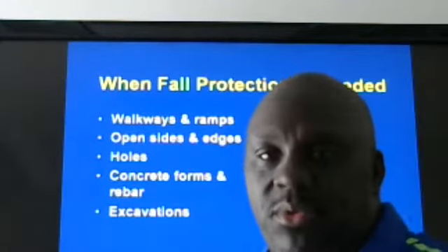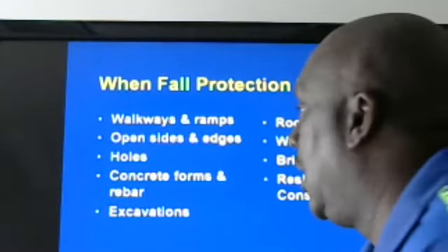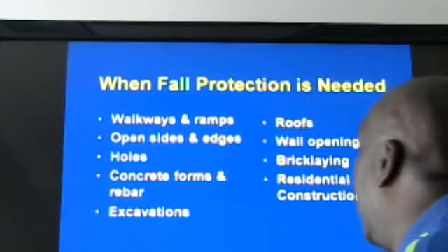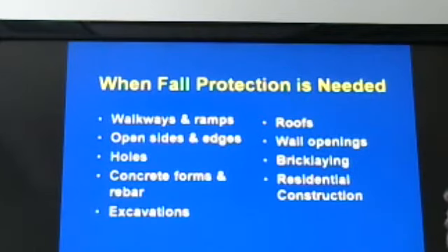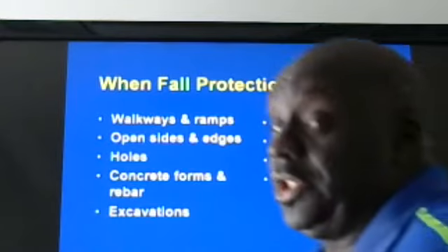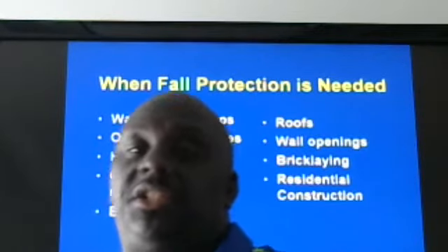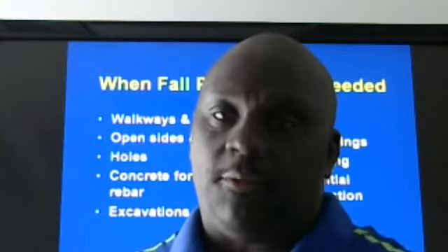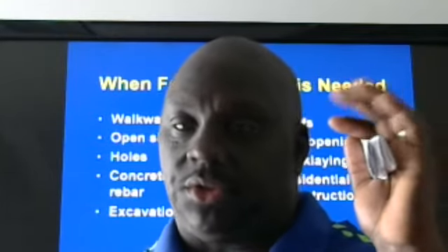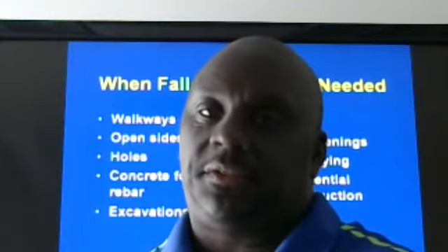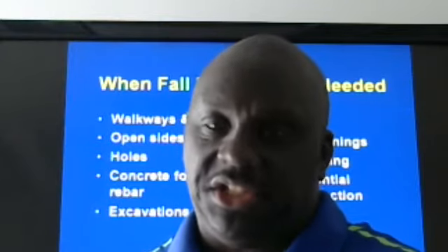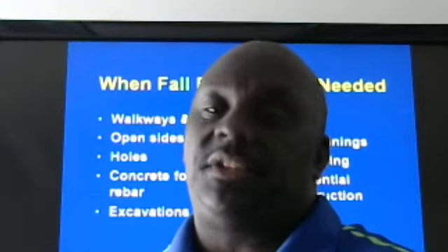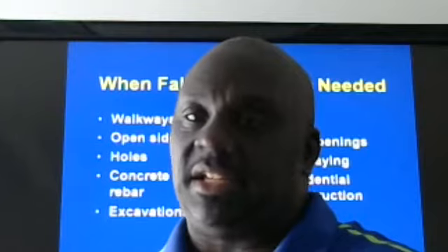It says ramps, walkways, open edges, holes, concrete, foams, rebar, excavation, roof, wall openings, bricklaying, residential construction. Guys, fall protection is needed at 6 feet. Regardless of what you're doing, at 6 feet, fall protection is needed. It's very, very simple, very easy to understand.